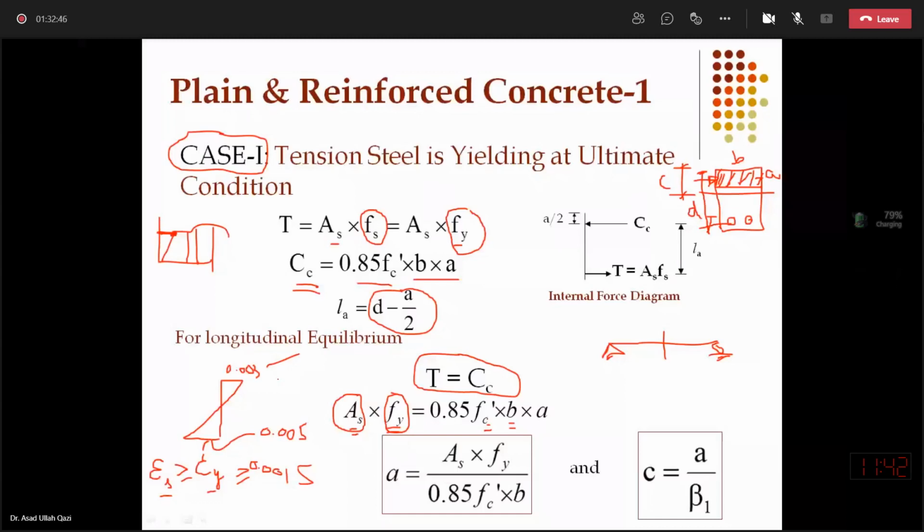except where is the neutral axis depth or Whitney's uniform stress block depth. So for this case 1 beam, by writing a simple equilibrium equation with all knowns except one unknown, that is, where is the neutral axis depth, I will keep that unknown on one side and I will bring all knowns on the right hand side, and with very little effort I can get the uniform stress block depth.